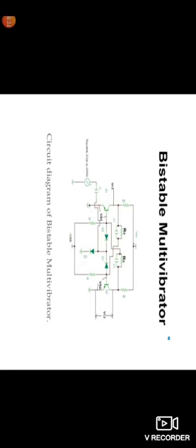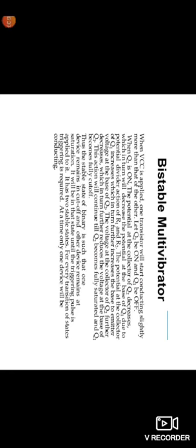There is only a small voltage across the base of transistor Q1, so Q1 is in the cutoff state and Q2 is in the conducting state. That can be explained. Also, due to the potential divider action of R1 and R2, the potential at the collector of Q1 increases.